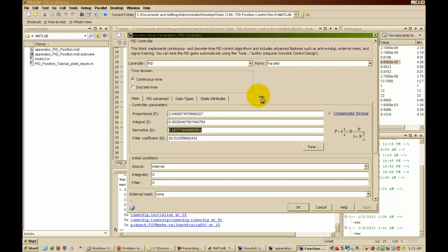The Simulink model I provide you to use to tune your gains is a generic model for any drivetrain configuration, so it should work for anything you need it for that involves a motor driving a load. Just make sure that you supply the proper motor parameters and calculate the motor load's inertia correctly, and it should work great for you. If you have any troubles at all, please just post a question.